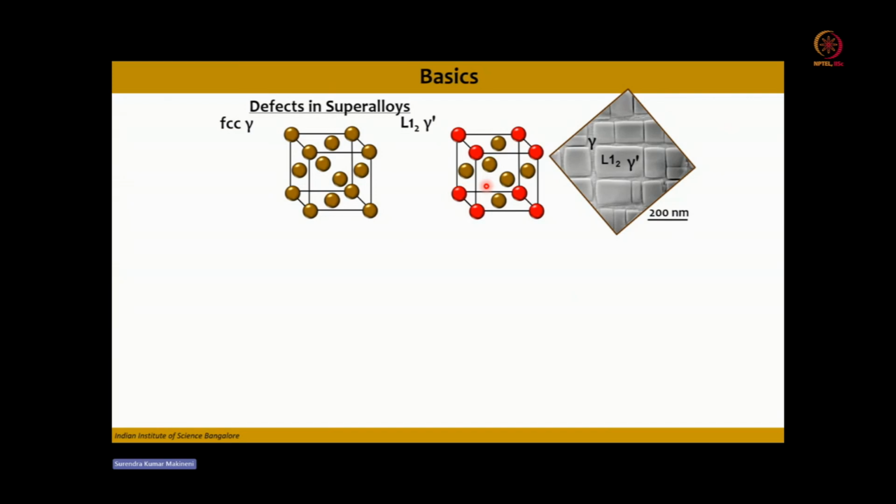Fine. So in any unit cell, there is a vector which is called the Burgers vector, and for FCC, the perfect Burgers dislocation is a/2 <1 1bar 0>. This is defined as the smallest vector from one lattice point to another lattice point, along which the lattice can shear.